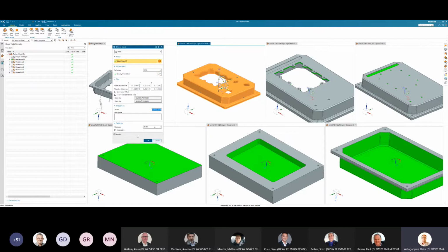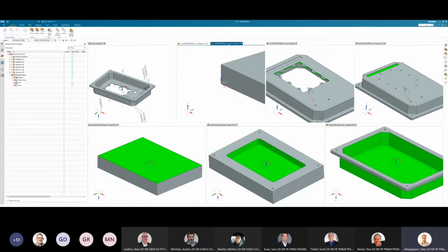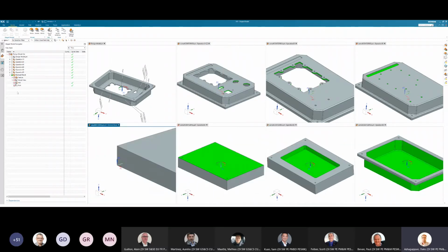It also gives you the stock size and the blank size. So if it is a shape something like this, I would use the block as a derived stock. If you have a shape closer to a cylindrical shape, we do have the cylindrical option there. So you can go and select this. I can simply say here, this is going to be my derived stock. When I continue this, it does create a stock for me as a last stage.